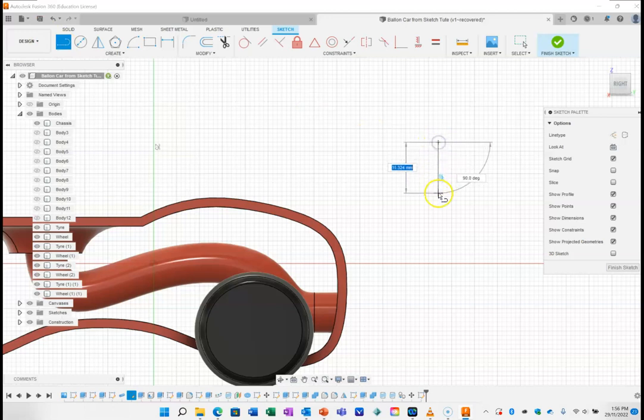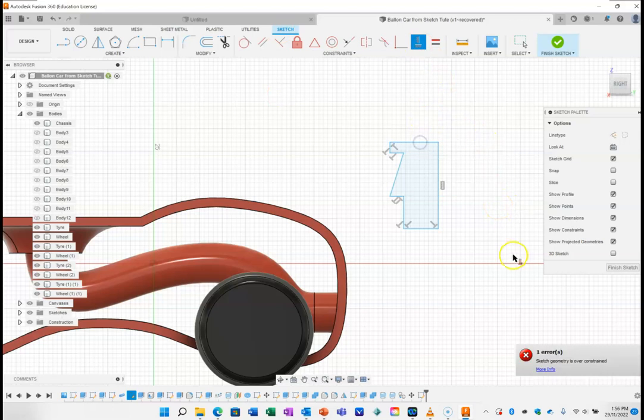So the spigot is going to be a line down here like so. That's going to be the middle of the tube of the spigot. And then we're going to go out about this far, making sure we don't press on that plus. So we'll just go out about that far. We'll go up here. We're going to go out here like so. It's going to go up at an angle. Then it's going to have a bit of a rectangular section going across to there. So that's my spigot. Just let's make sure that this is definitely vertical. Got an error there, so that's fine. So these are the sizes that we're going to do.